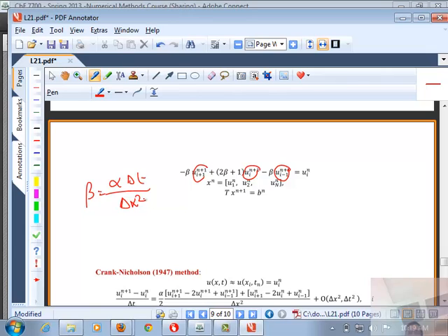So each time step requires additional computational effort by inverting this matrix. But for a linear problem, it is a constant matrix, so you need to invert it only once. Then it is just a matter of a new right-hand side coming every time and doing a matrix-vector multiplication. Efficiency becomes very important if you have 3 spatial dimensions and 4 equations.